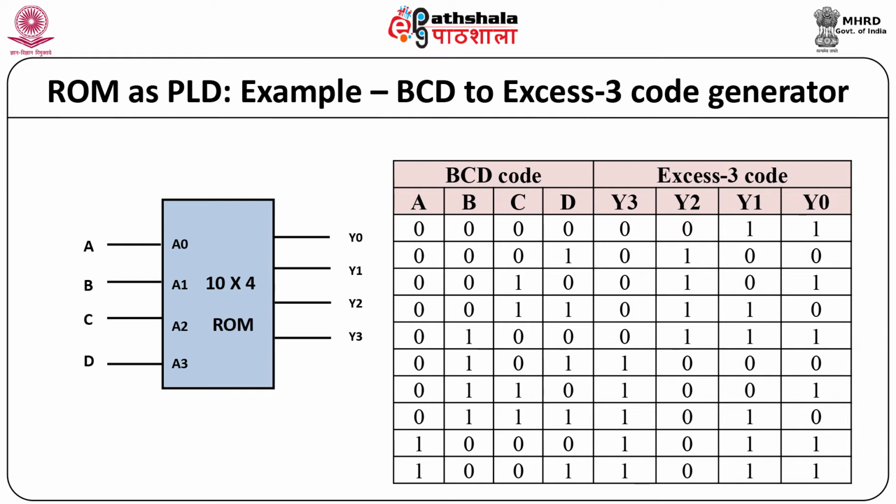As the number of inputs to the truth table is 4, there are actually 16 possible combinations in binary, but in BCD we restrict ourselves to only 10 possible combinations corresponding to binary coded decimal numbers. So, there are 10 different memory locations required in the memory. Each location is capable of storing 4-bit data which is addressable by the ROM.